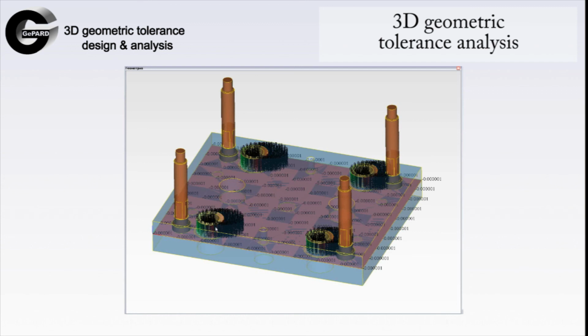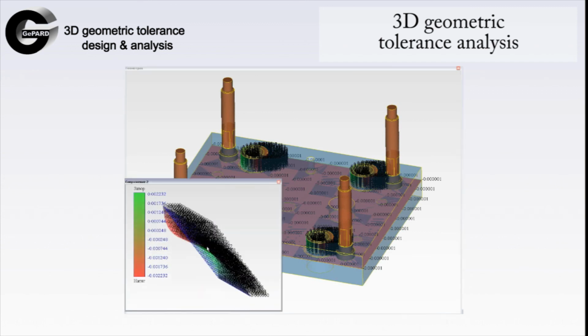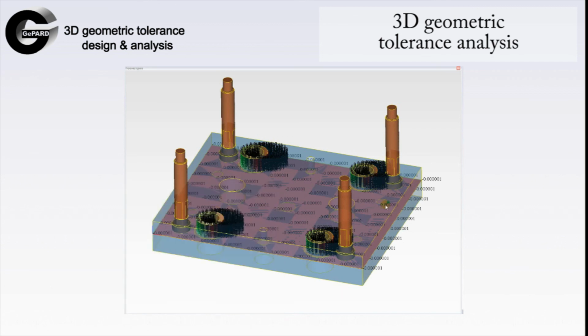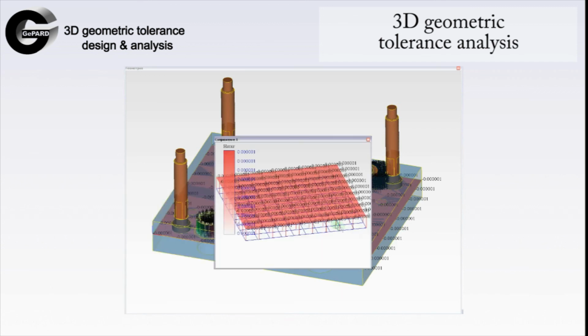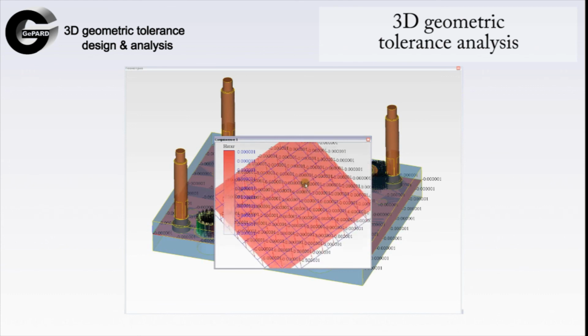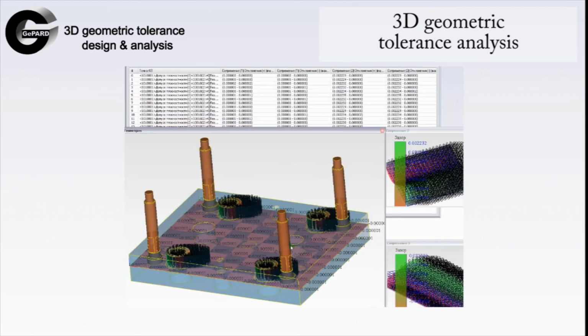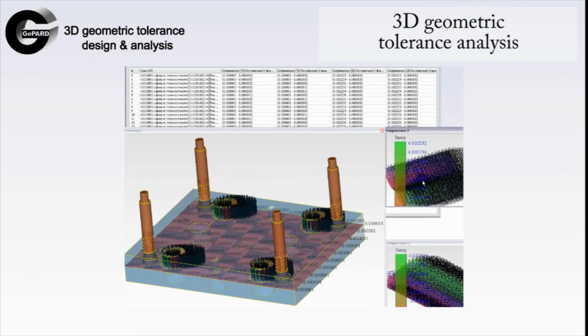By selecting a surface on the 3D assembly model, one can view the analysis results on the accuracy plot with clearance and interference values in every point of the configuration space. Also, one can view the maximum clearance and interference values in the assemblability analysis dialog box.